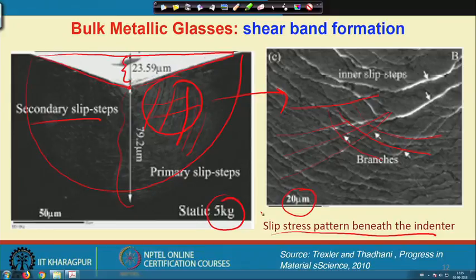So, definitely the plastic deformation in these glassy alloys occurs by the evolution of shear bands, and this inhomogeneous deformation occurs at a temperature lower than the glass transition temperature. However, the deformation could be homogeneous if we increase the temperature, and a steady state or non steady state flow can be seen, depending on the value of the n constant.